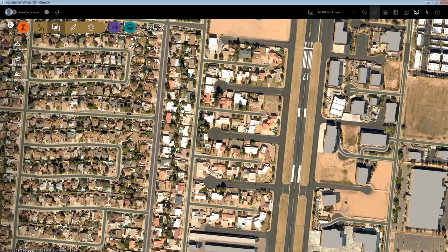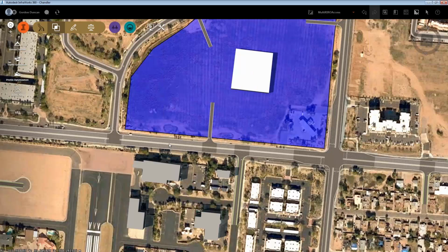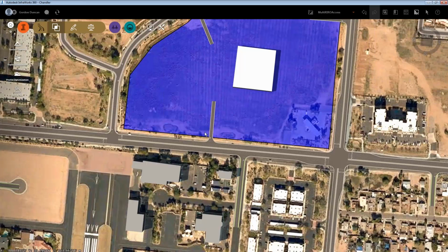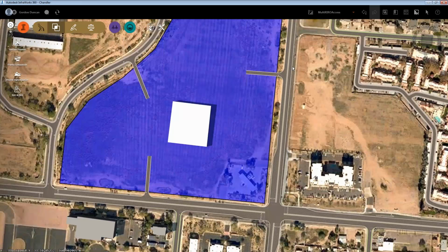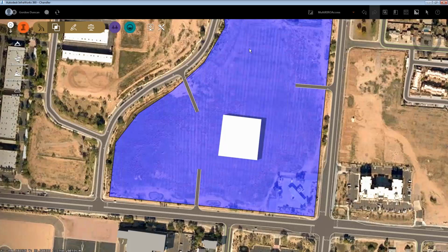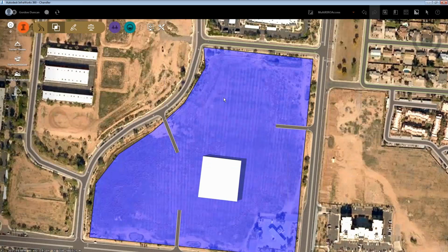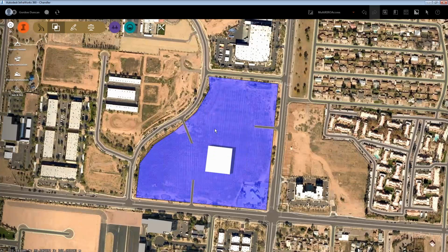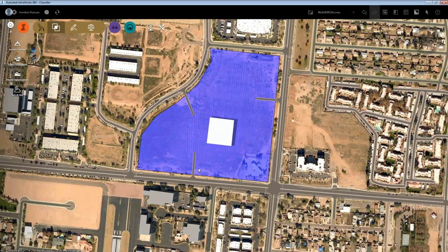We've created two of those on both of the major roads, one there and one there, and we've also created an all-access intersection on this minor road that goes around the back. And that's actually a lot more roadway work and three intersections to create rather than one. But someone might say, well, I think we want that because otherwise you're going to have too much effect on the through roads, and we don't want that sort of disruption creating extra queues.